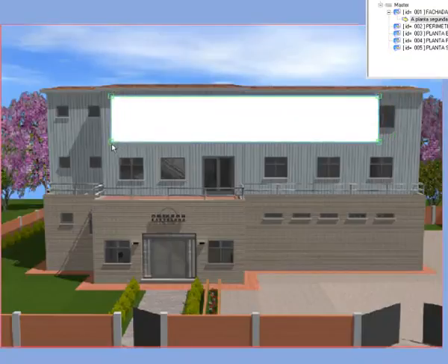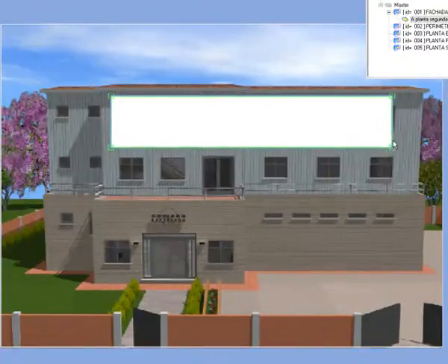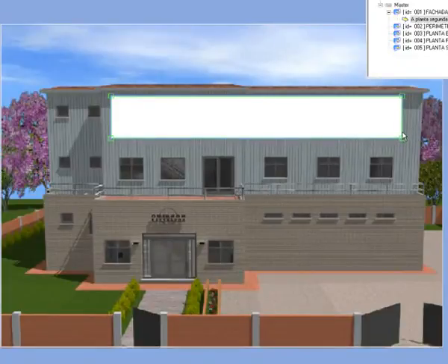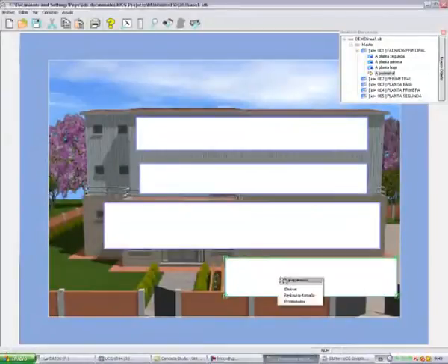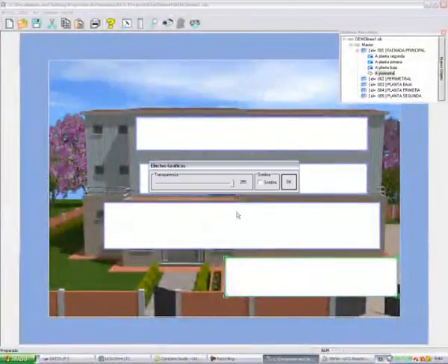We'll add more objects area type to link with the other synoptics. Placing the mouse over the object, and clicking with the right button of the mouse, we have access to the area properties window. Once the area type objects have been placed, we'll modify them to make them transparent and make that the borders are not visible.